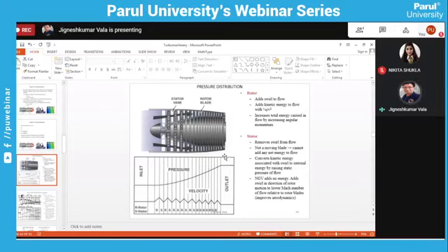But what is the main working principle of the stator? The main working principle of the stator is to remove the swirl from the flow. And this is not a moving blade, so we cannot add any net energy to the flow. It converts the kinetic energy associated with the swirl to internal energy by raising the static pressure of the flow. So using the rotor and stator with a number of stages, we can raise the pressure and increase and decrease the velocity.